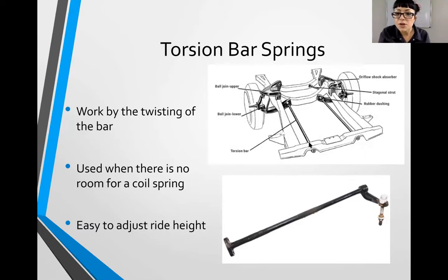Well, what they did here is they took the torsion bar and they attached it like a puzzle piece. If you remember when you were a kid, putting the square in the square hole, it fits like a puzzle piece, and it's usually like a hex shape. So we've got a torsion bar that is put in like a puzzle piece into our control arm, so it can't spin. It turns with the control arm. So as the control arm moves up, my torsion bar spins at this end, right? So if I've got a bar here, as this moves up and down, that's gonna spin. I'm using my arm as a piece here, but hopefully you get the point across.